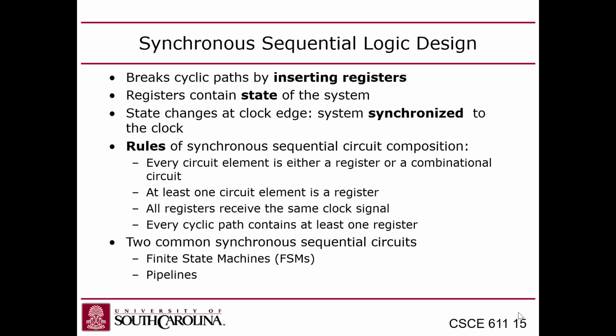The book has some rules for synchronous logic design. I mentioned the registers contain the state of the system. State changes at the clock edge, so the system is synchronized with the clock. And then the rules are: every circuit element is either a register or a combinational circuit. So what else is there? Don't put latches in. I think that's the idea. At least one circuit element has to be a register. If not, then it's just combinational. All registers receive the same clock signal. Now think about that.